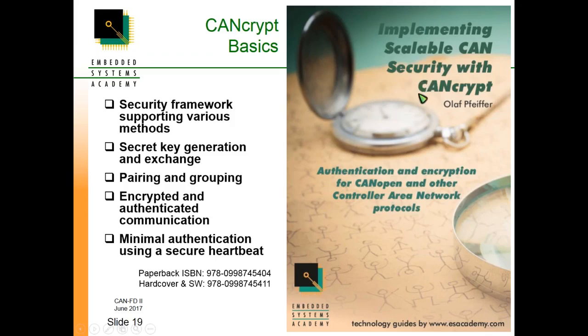It's not really focusing on very specific methods. It's more of a framework supporting various security methods. One of the core functionalities that we'll also use in the bootloader is the secret exchange of keys in a completely different manner. So it's really a very CAN-specific encryption here. We'll talk about that. Then we'll have a pairing mode with encrypted and authenticated communication. The idea here is that only an authorized communication partner should be able to hook up with the bootloader and issue commands like delete the flash or even activate receiving a new code file.